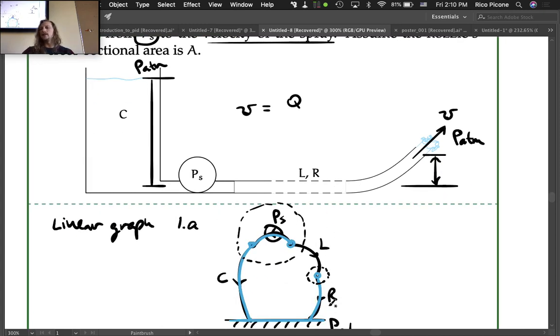I would say the closest is R, the resistance, so Q sub R. That's in SI units, meters cubed per second. If we would like to turn a volumetric flow rate into a velocity, we have to divide by the cross-sectional area, which the cross-sectional area of the nozzle is given as A in the problem. So what we're really looking for here is QR.